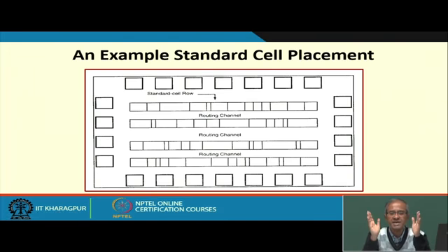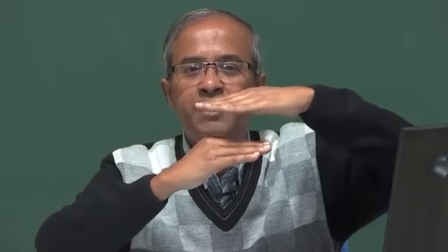You see, for standard cell the problem is not difficult. If you see later on that your space is a little less, you can move the entire row a little up or down. Okay? So, those adjustments you can do later, but for a general, say, a full custom thing where there are so many blocks, moving a block around is not so easy, because moving a block to make space here might make the space on the other side less, that can create a problem, right.